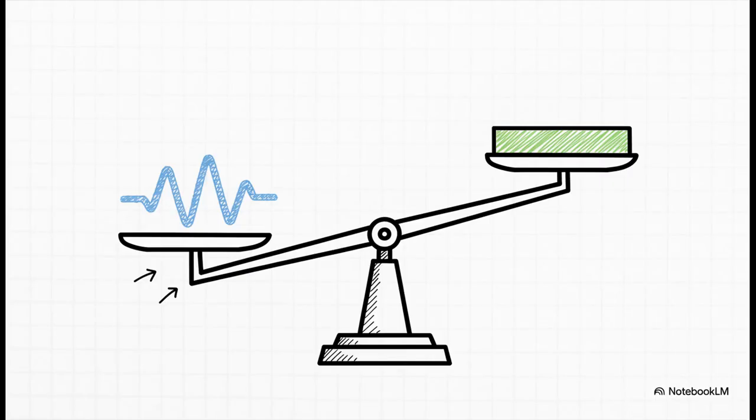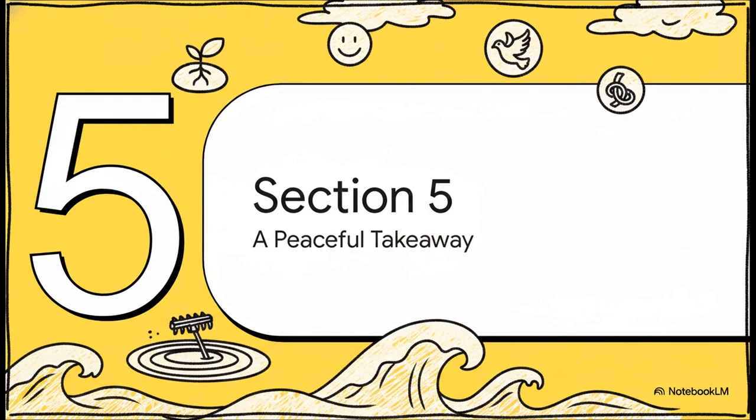Because ultimately, RMS is just finding the balance point. Think of it as finding the steady DC equivalent of our rhythmic AC wave. It's essentially a way to calculate the real effective power that our resistor is dissipating by treating the wildly waving current as if it were just a flat, steady, predictable line of direct current. It allows us to apply really simple, steady-state logic to a dynamic, alternating system. Pretty clever, right?